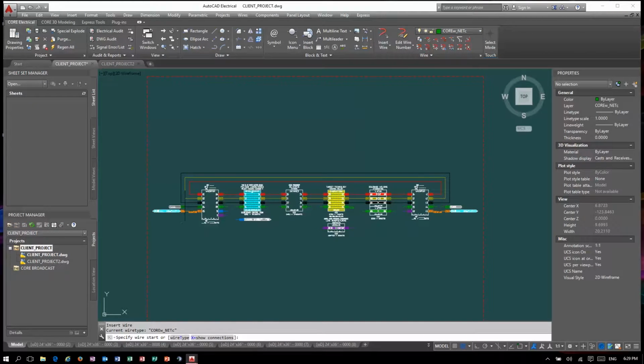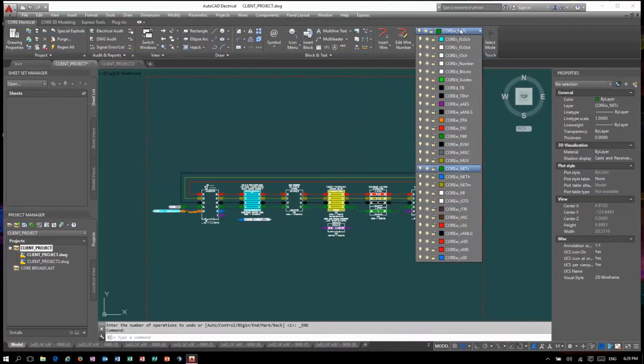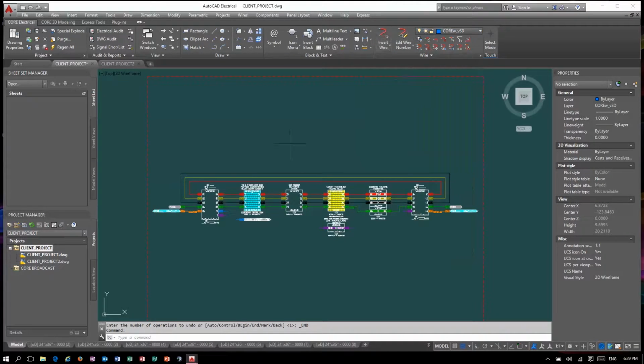One of the biggest benefits in using Electrical AutoCAD to lay out your system is its ability to understand what wires are. By default, Electrical AutoCAD will not allow you to intersect wires. It will instead jump over any perpendicular wire in its path. Unlike in other AutoCAD versions where you have to do this step manually, this is an automated feature. It also provides you a tool to swap the direction of the hop from horizontal to vertical or vertical to horizontal. In electrical, this is called a wire gap. When designing complex wire networks, this is a huge time-saving feature.